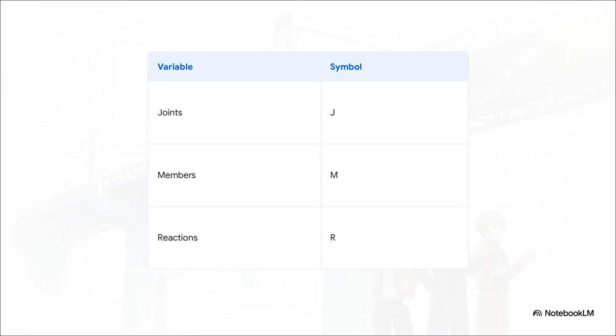The cool thing is we can boil down the physical complexity of these massive, sprawling frameworks into a single, clean equation, using the variables straight from our Arabic source text, where joints or nodes are ta, members or physical rods are dod, and reactions or support forces are ra. The formula dictates that 2 times ta must equal dod plus ra. Literally every single connection point, every steel beam, and every concrete support is accounted for in this one simple balance scale.